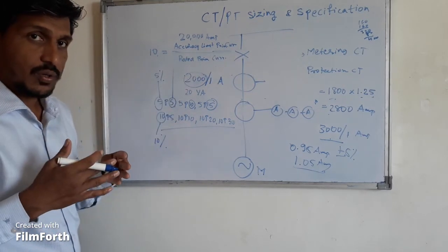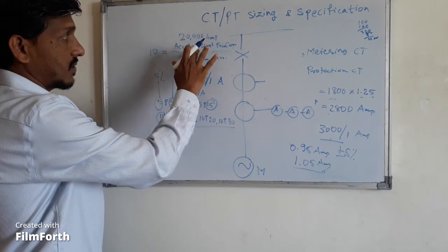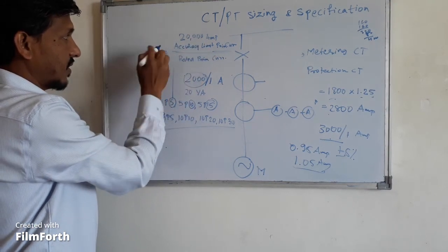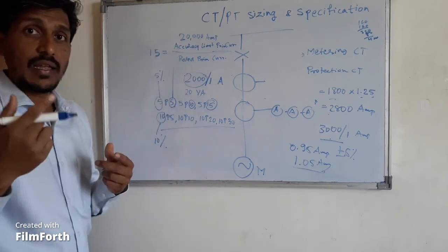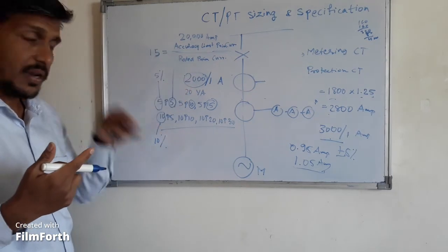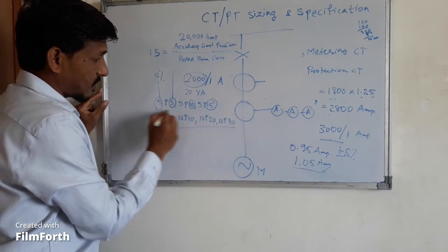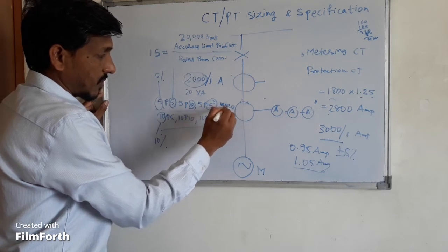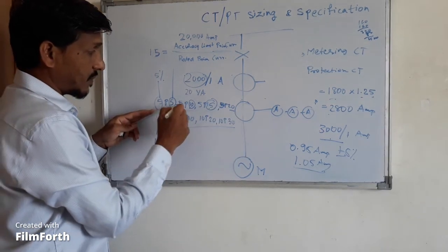It is a ratio. This means when your primary current is around 20,000, or if it is more than 10 times, or 15 times if your ALF is 15, so till your current is 15 times your primary current, the error will still be 5%. It means that. If you see the specifications 5P5, 5P10, 5P15, even 5P20, the more the ALF, the better the CT, because the error is the same 5% everywhere.